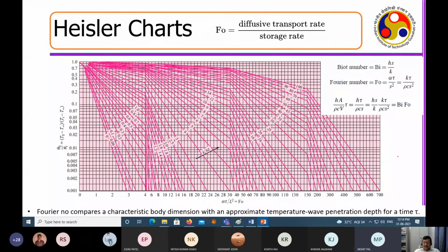Okay. So just to clarify the whole point. Suppose this is a boundary, and here I define the temperature to be T0. That means I have fixed the temperature here. But suppose you have a boundary like this, and I have put an insulator here. What is the boundary condition that I put here?